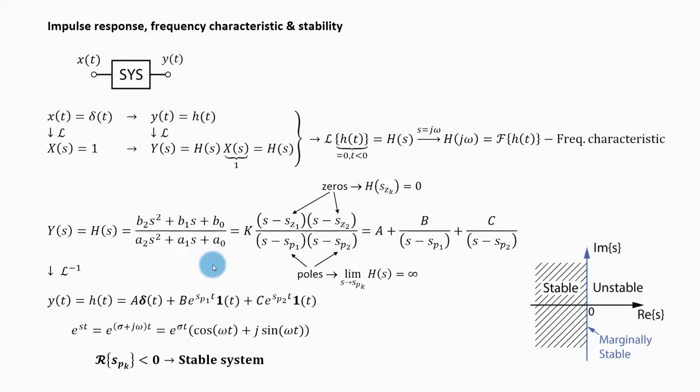So you can judge the properties of your system from the poles of the transfer function the same way as you did it for the roots of the characteristic equation. In fact, this covers not only stability, but it also pertains to damping. And a side note, this complex plane where we draw the values of s, we also call the s-plane.